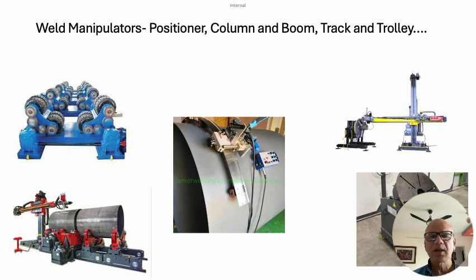It's almost becoming like a machining process, and you have different kinds of machines which are available along with the welding machines. The basic power source, like in any machining process, you have a spindle, whether you are turning it or you are boring it, milling it, you must have a spindle, and then the manipulators to move the job to create relative movement between the spindle and the job. So similarly, a relative movement between a welding head and the parts to be welded is required to be achieved. Let's move to the next one.